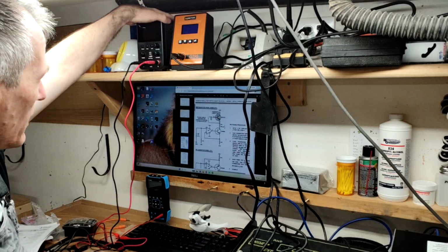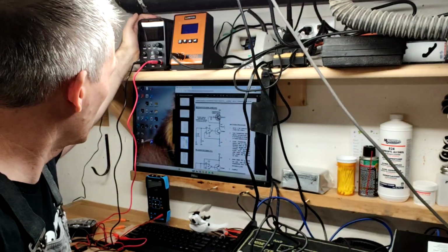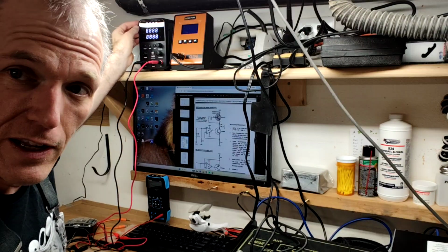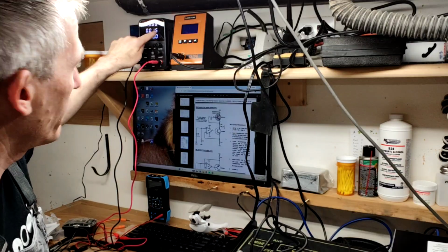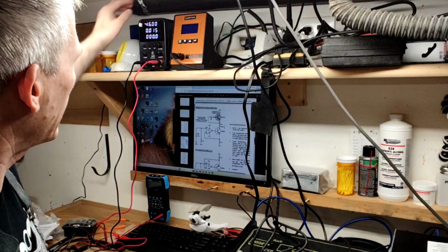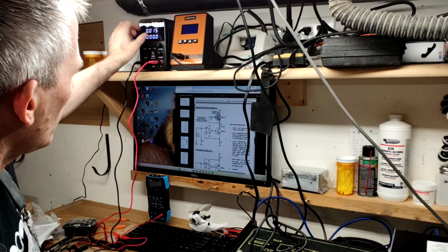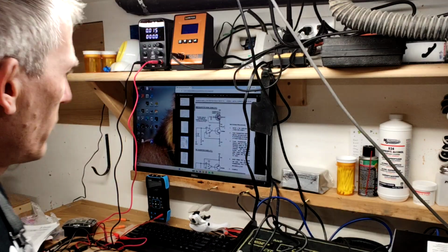I want to also mention this power supply. This is a super important tool to have when you're doing electronics, because this one is current limiting, right? So you can dial in an amount of current. I have it set at 15 milliamps because I know that's not going to burn anything out too badly. And we can adjust the voltage to be whatever we want. And so for this test circuit, 10 volts.